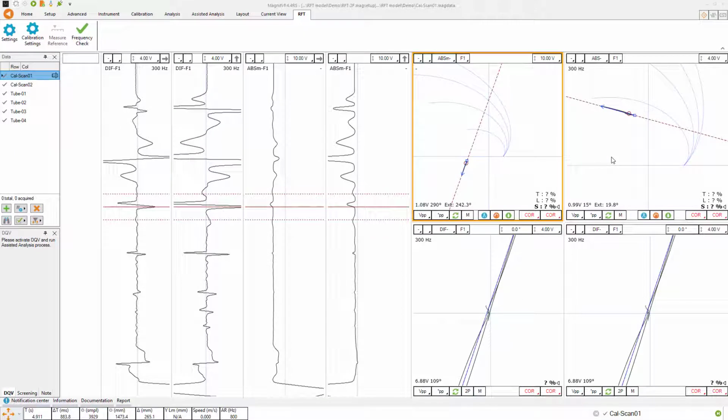Let's start with an unknown calibration tube for which we're not sure of the optimal frequency. In this case I recorded a data file of the cal tube with a frequency that was too low for the material properties. Normally, to calibrate the remote field data, we first have to measure the support plate manually in the voltage plane and then do the usual calibration. So let's start by calibrating the old model and then we'll do it with the new model.